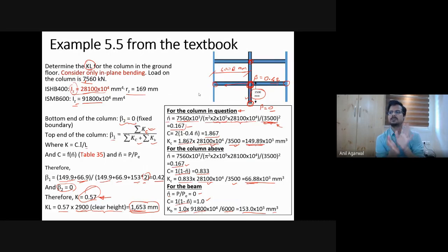Okay. But yes, when you are looking at the effective load capacity of a column, you should be looking both about the minor axis, major axis. For major axis, you have to worry about these restraints also. In the minor axis, mostly these restraints won't be available because the connections themselves would be typically pin connections.